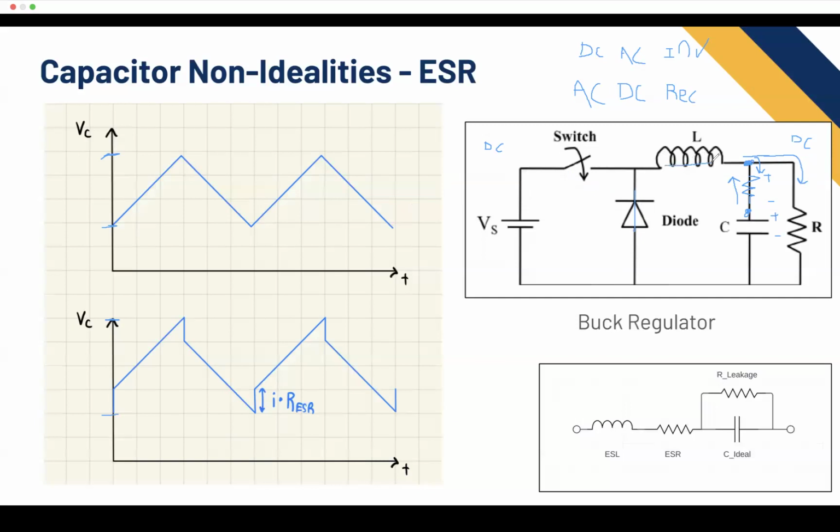So it's going to keep pulling current as it slowly ramps down, and that current will come through the diode and keep powering this system as the energy in the inductor slowly decreases. And then the capacitor is for filtering, so it has some ripple as well. That's what we have drawn over here on the left.